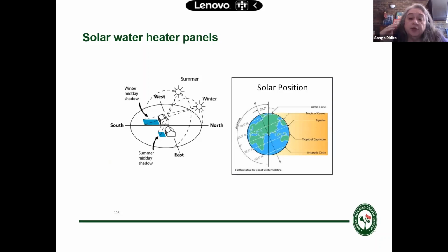And what they did is they put the wall right in front of the solar water heating system, so that solar water heater never sees the sun because the wall blocks it from any collection. So these are the kind of things as well. Sometimes you look at your plans, you go, oh, there's a solar water heater, tick the box, it's there. Please also look at whether it is facing the right direction, and does it have anything that can potentially shade it?